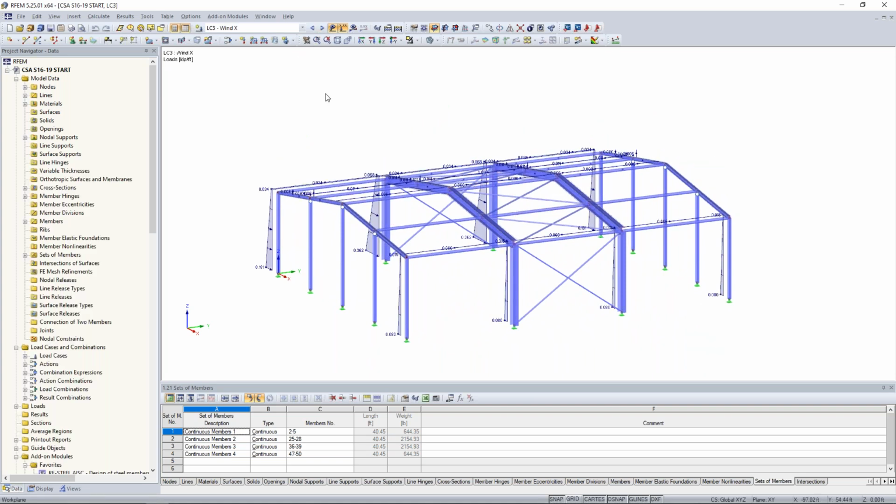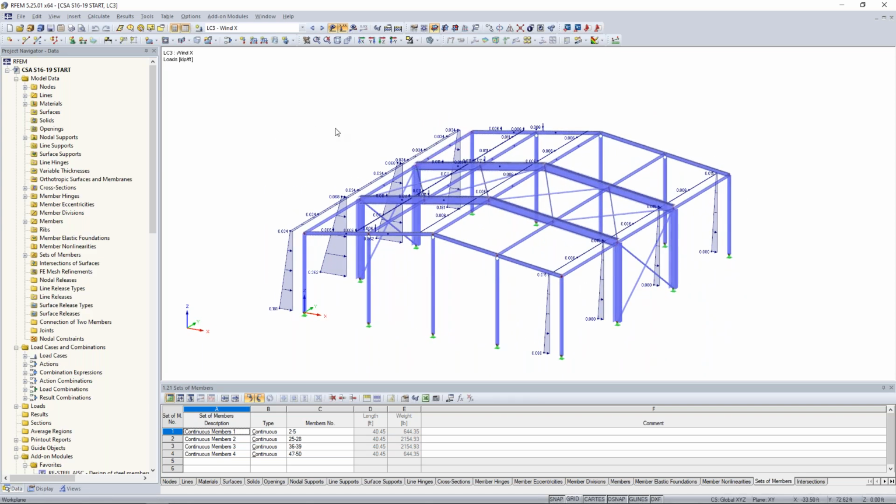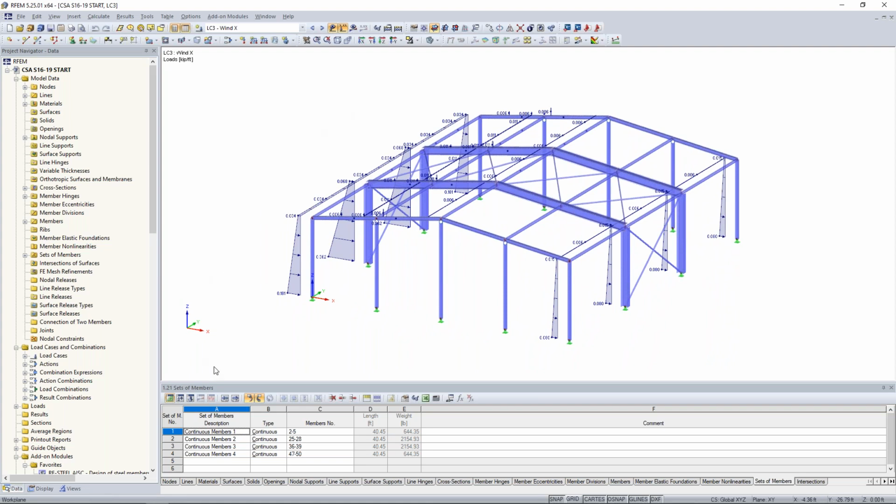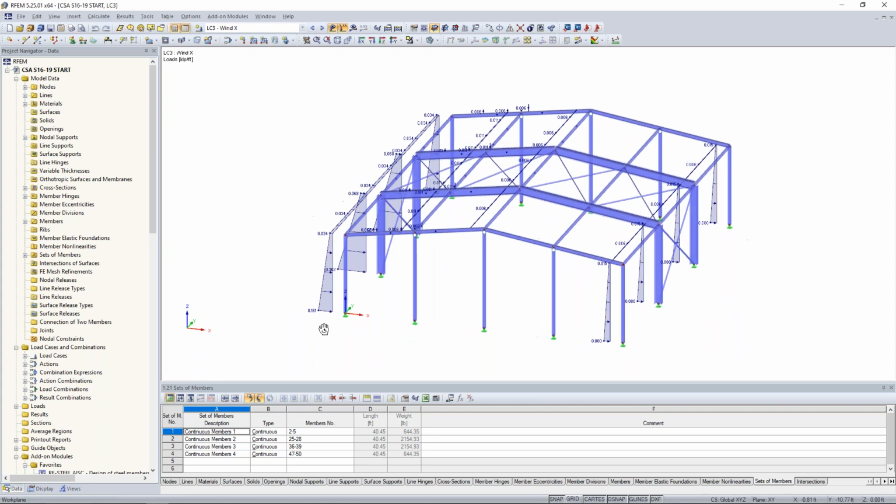So I've also applied a wind in the X direction, pretty simple application here. According to the global X axis, we have our wind flow from left to right. Over on the left for our pressure face, these are just standard member loads that I've applied to each one of these members. Over on the right-hand side, we kind of have a suction force,